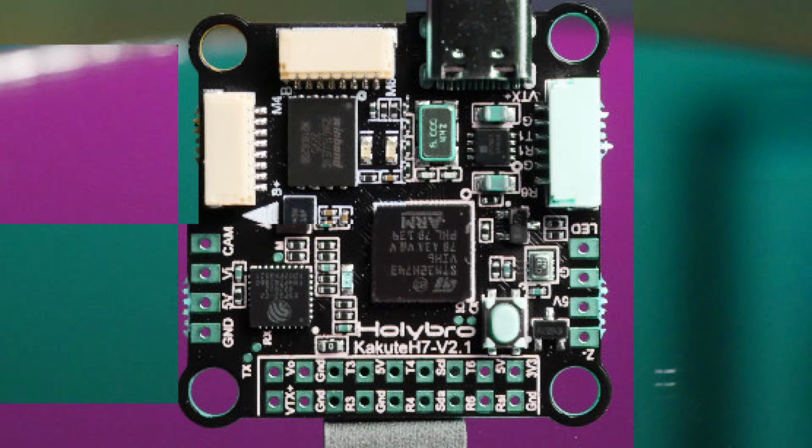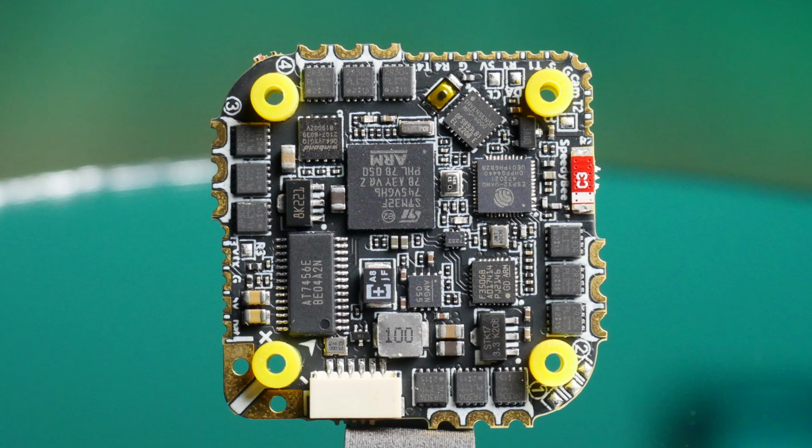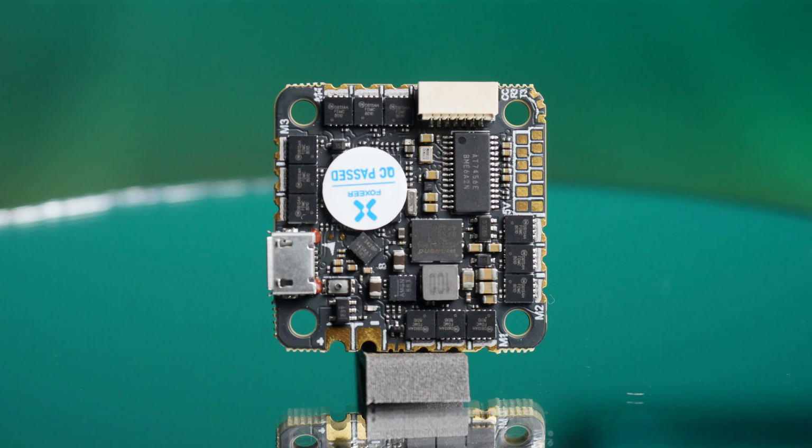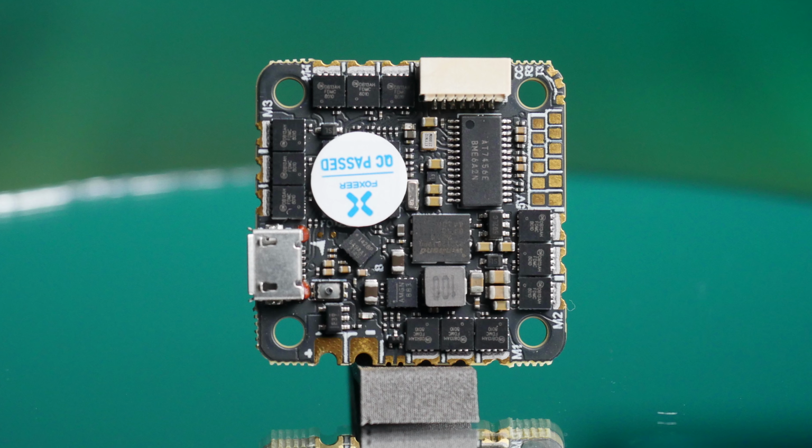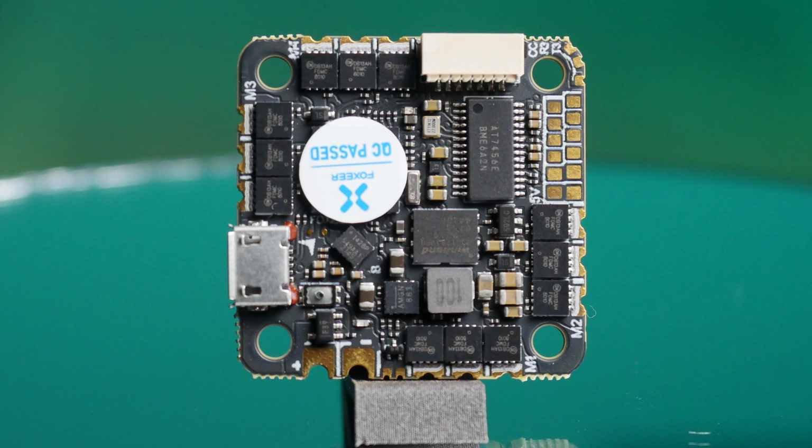Then the multirotor flight controllers can be divided into two subcategories: the general purpose flight controllers and all-in-ones. All-in-ones, just like the name suggests, have everything in one. Especially, they usually have built-in ESCs. With the all-in-ones you just don't need separate ESCs or a 4-in-1 ESC to connect to the brushless motors. Everything is integrated on one small board.